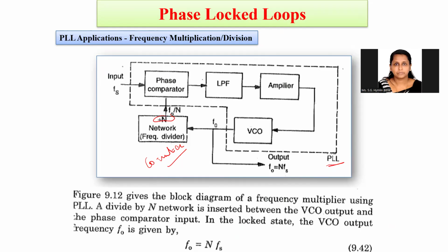If the input signal is, for example, a square wave or pulse train, the VCO can be directly locked to the harmonic of the input signal corresponding to the Nth value. However, the amplitude of the higher order harmonics decreases, so if you increase the N value, the effective locking may not take place.